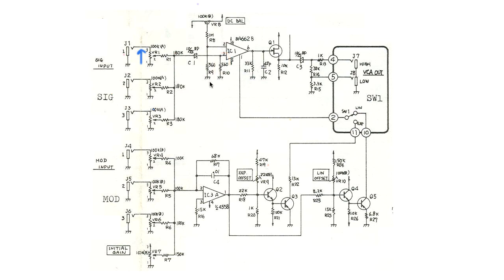And in fact, there are companies that will sell you very expensive boxes that are not really anything more than some jacks and some resistors. And these are called passive summing boxes. And they'll put these shunt resistors in the network to try to eliminate some of those weird effects you get when you connect or disconnect various inputs. But this does also have the effect of attenuating your signal a great deal.